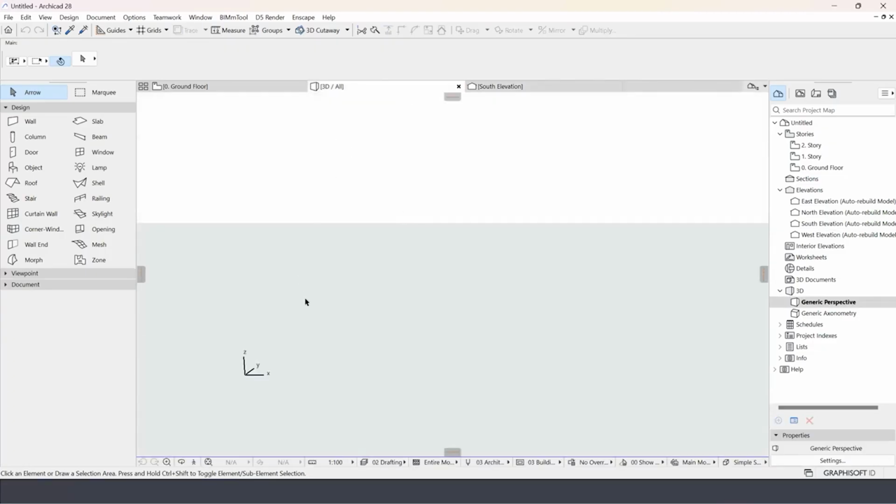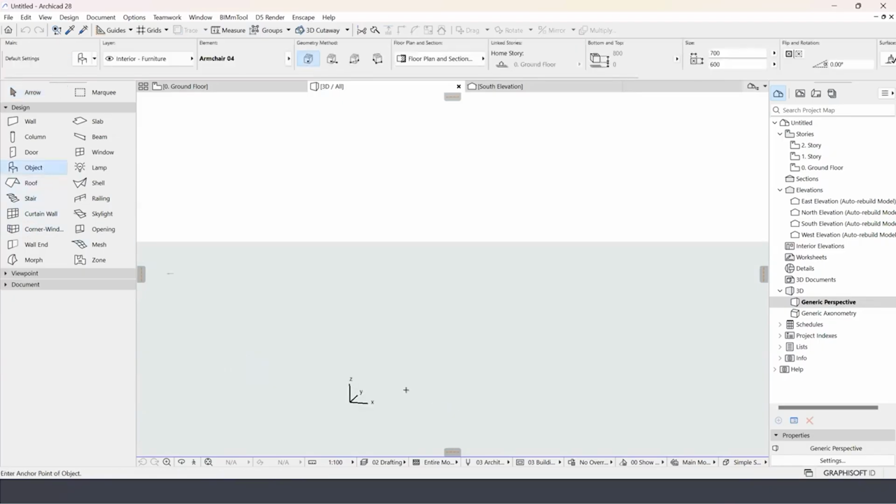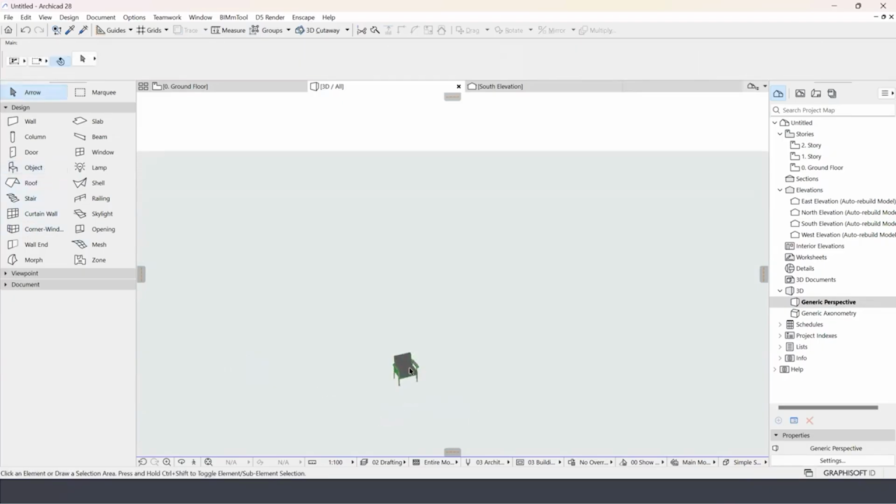And if I go to 3D, the only small difference is that if you use shift and middle button, you get to orbit around. For example, if I have, let's say, one chair here, zooming in and zooming out is the same. If I use the middle mouse button and hold it, it will pan around the model like this, more like a drag. You're not dragging the element, you're just dragging the camera position. And this is the origin, so you can relate it to that. And if I'm using the middle mouse button and shift, it is going to orbit around that particular object.